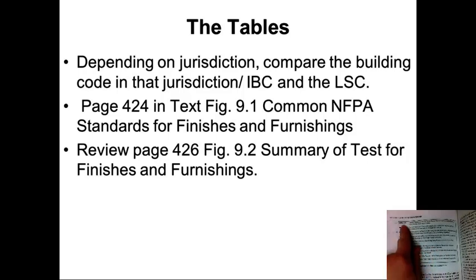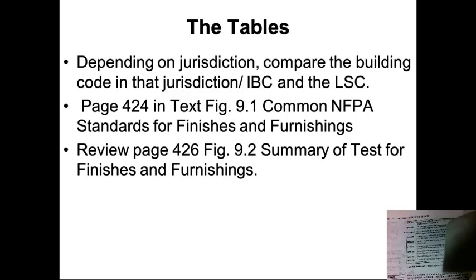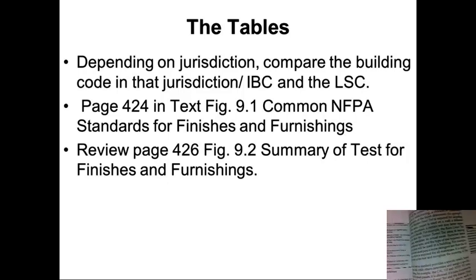Read and know what the NFPA 253 is. Okay, standard method of test for critical radiant flux of floor covering systems using a radiant heat energy source. So that kind of goes to your radiant panel test. I go through and make sure that I know which test method goes to what. Okay, the NFPA 260. So you're going to go through all of these, and you're going to determine which ones those are. So make sure that you do that so that you can understand that.